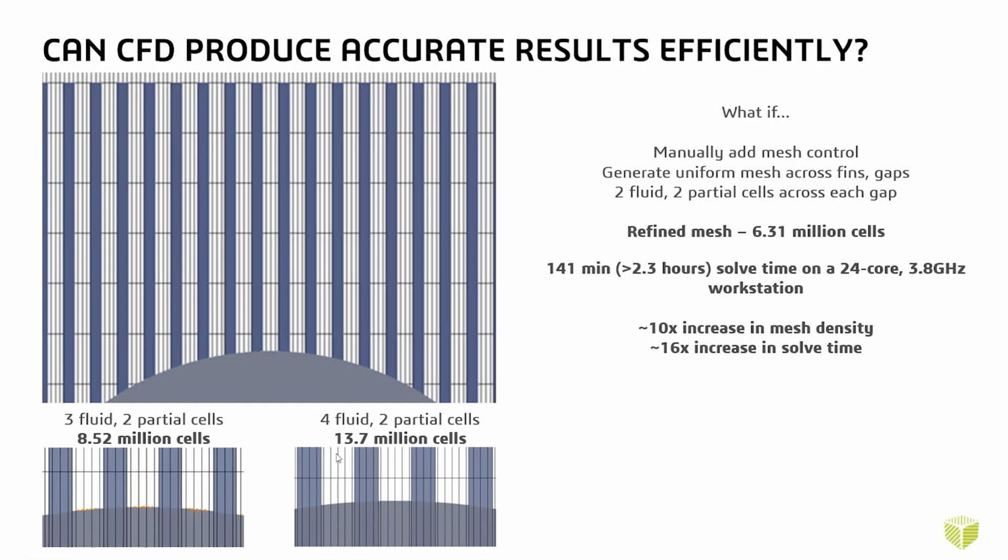So I really would not want to do this when I'm trying to do fast iterations, but I would likely take advantage of this when I get into the more detailed final analysis, where I'm trying to look at the temperatures in the battery cells in a more final design. But I should also understand the inaccuracies that I brought into this by using these high aspect ratio cells. Those can bring in inaccuracies, and I should be aware of what that's doing.